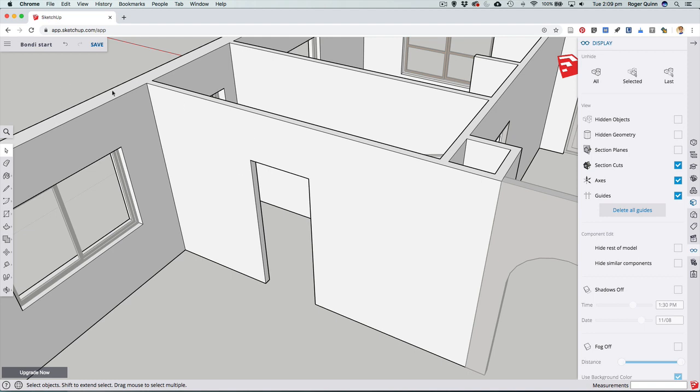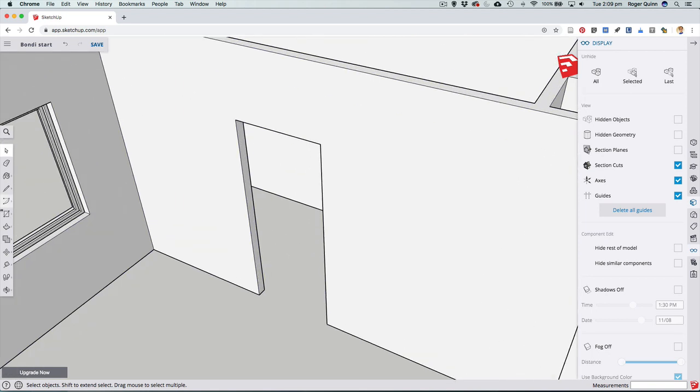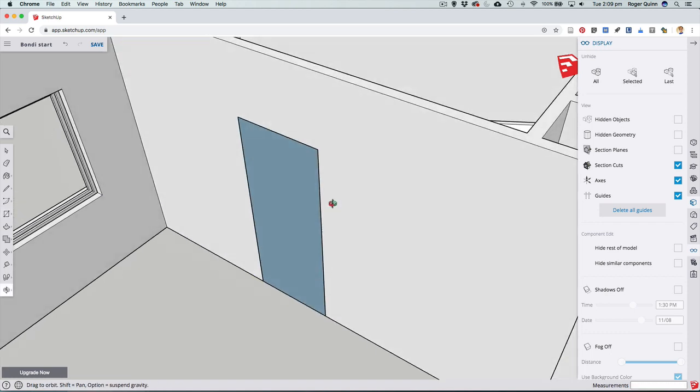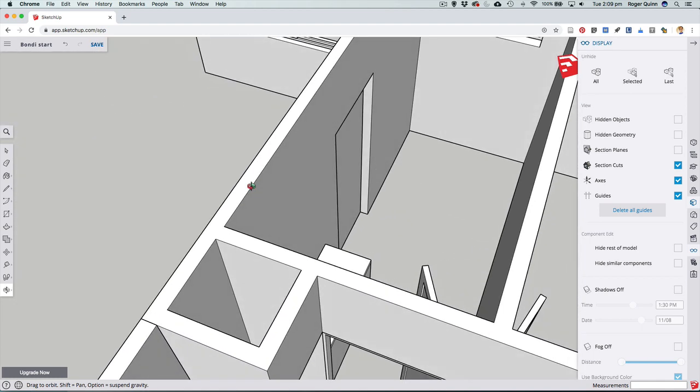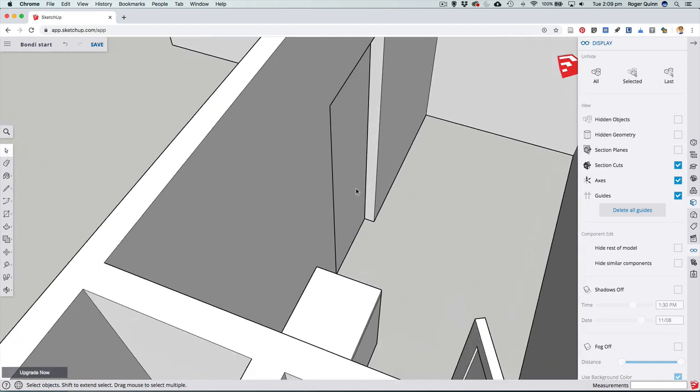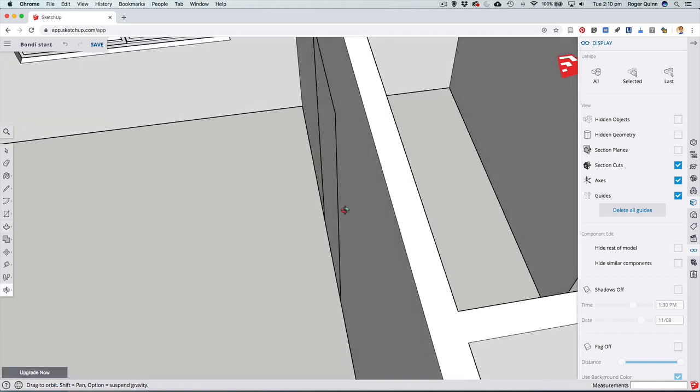Now I'm back into the same procedure that I was using before to make a frame and then a door. I've got it out of group edit mode for the walls, and I'm going to draw a rectangle over that space and push pull that through to give it a thickness. In the case of door frames, they usually go right through to the same thickness. The windows I made slightly shorter than the actual cavity, but in this case I'm going to go right through.